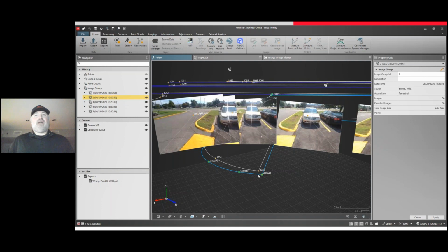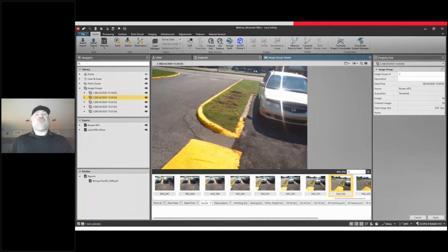How this line work was plotted wouldn't make or break this project, but it does outline how the image data can be used solely on its own, without any additional image processing, for verification and site awareness. The 10 minutes it took out in the field to take all of these images with the GS18I could alleviate a return visit.